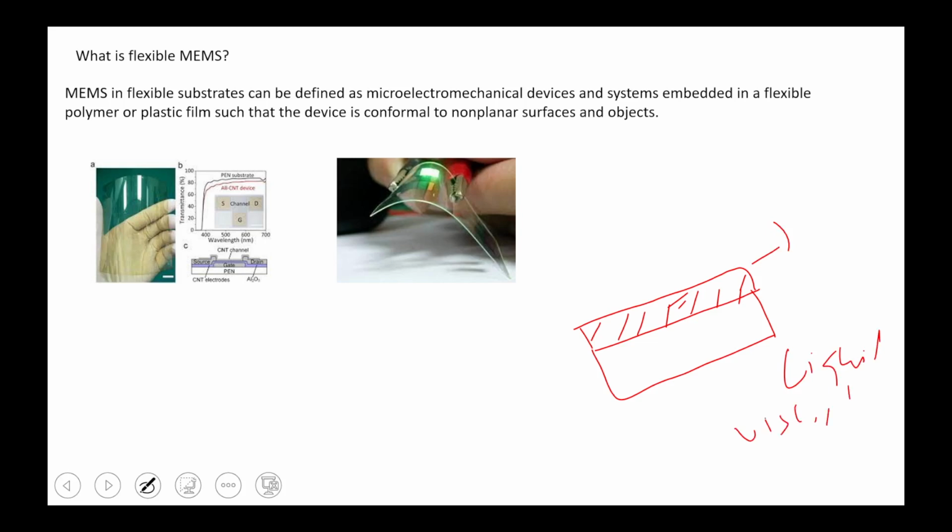When we drop cast, the photoresist, for example SU8 or PMMA, remains in liquid form during drop casting or spin coating, and it coats uniformly. Then we do the soft baking around 40 to 45 degrees to make it hard and to evaporate any solvent during the heating.